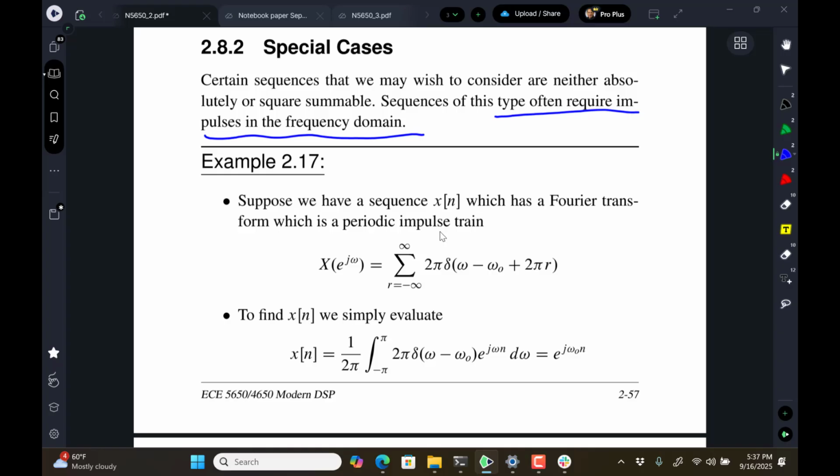Now I say encounter because that's another example that I'll drill into, and that gets into the spectral analysis problem. If you have lots of cycles of a sine wave and you just truncate it and take that into your processing engine, it looks very much like a delta function. It doesn't have any other issues, but if you don't have a lot of cycles of that wave, then you get something called spectral leakage, and I'll drill into that too.